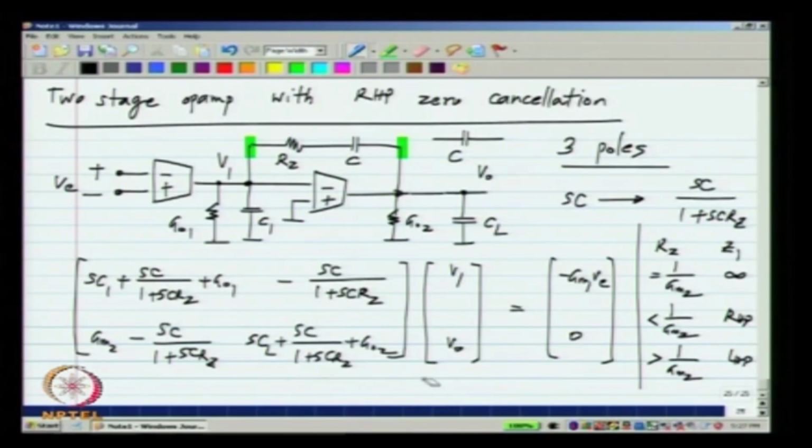Now, we will also have a third pole, and again by using a similar approximation as before, that is earlier to solve the quadratic equations we took two terms at a time and turned it into two linear equations. Exactly the same thing can be done for the third order equation that we have.